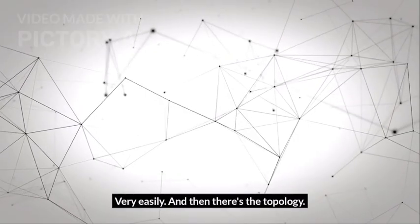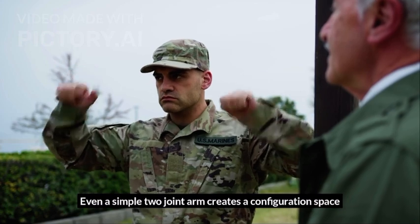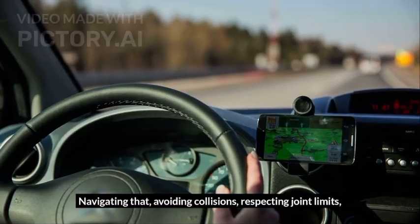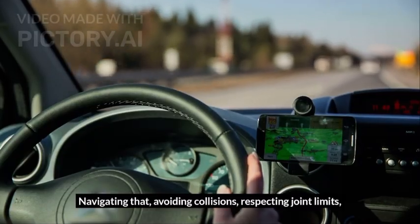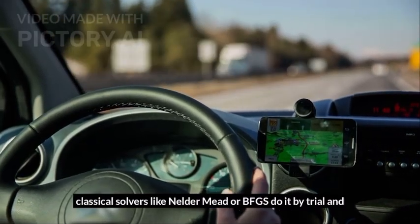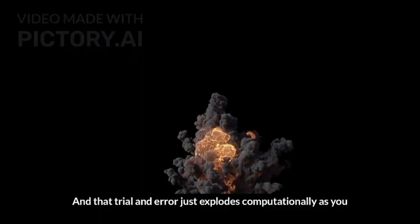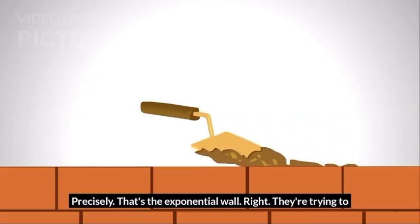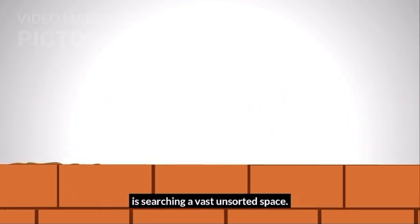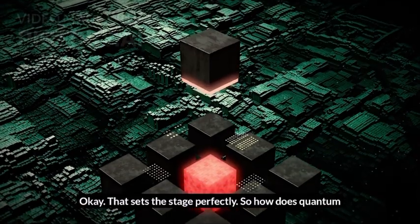Very easily. And then there's the topology. Even a simple 2-joint arm creates a configuration space shaped like a torus, like a donut surface. Navigating that, avoiding collisions, respecting joint limits. Classical solvers like Nelder-Mead or BFGS do it by trial and error, step by step. And that trial and error just explodes computationally as you add more joints. Precisely. That's the exponential wall. Right. They're trying to optimize, but the real problem is searching a vast, unsorted space. They aren't built for that scale of search. Okay, that sets the stage perfectly.